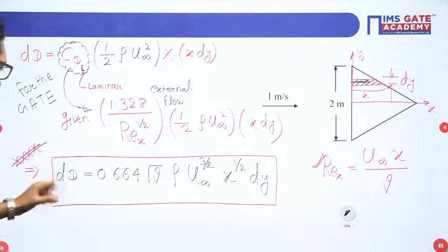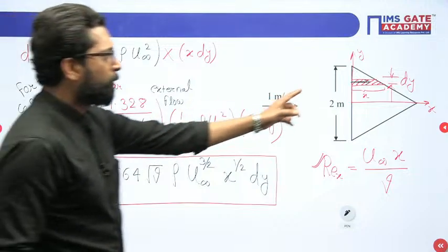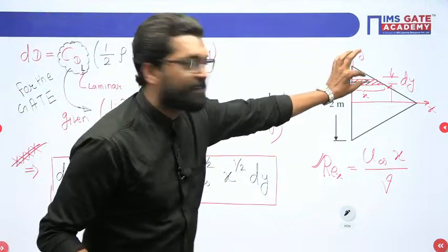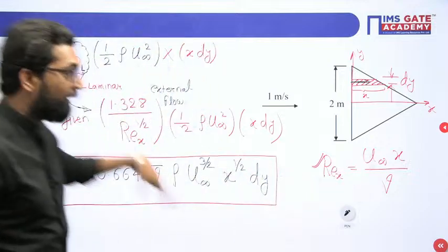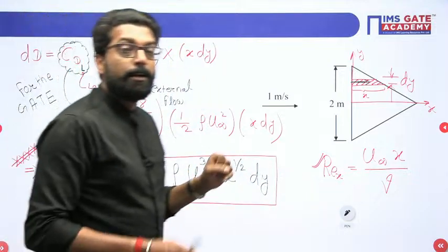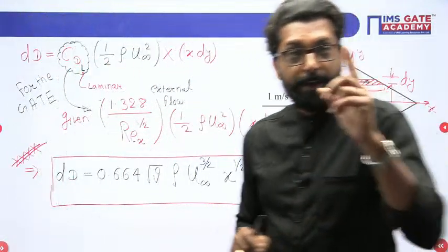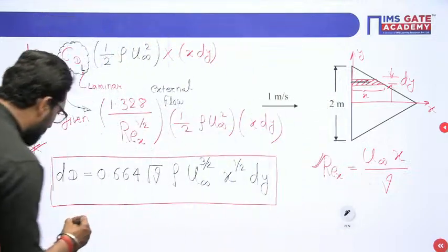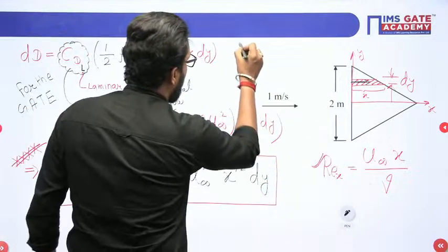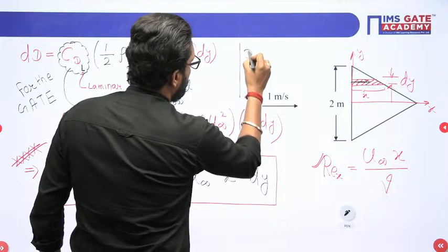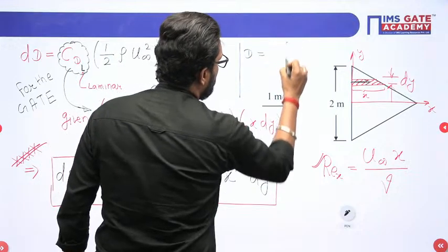Just do the practice. Now we have to integrate it. We have to find the total drag force on this element. Now, my dear, during the integration, be careful. We have to find the total drag, so if you find the total drag D, you have to integrate dD.